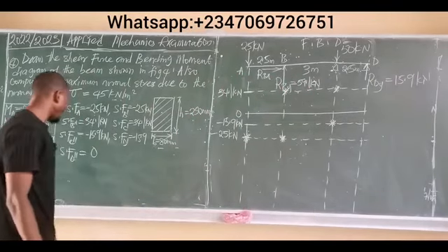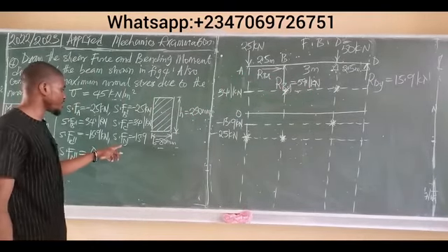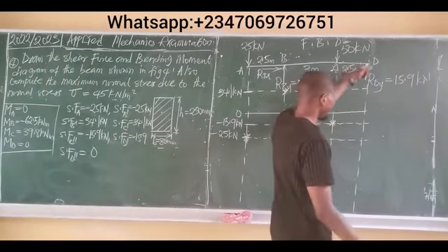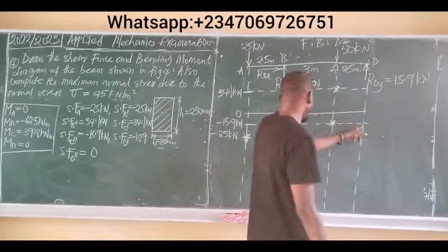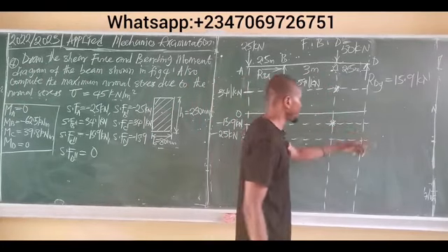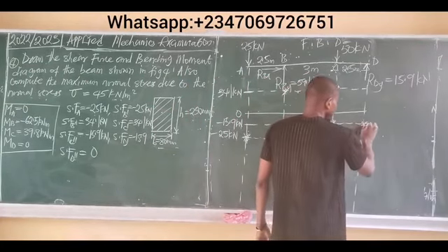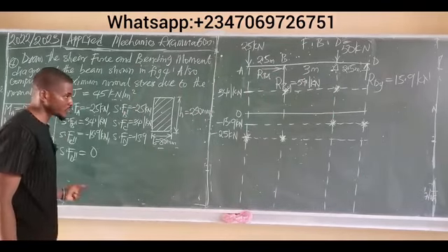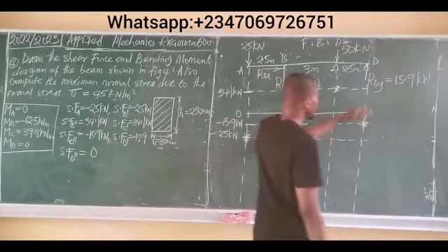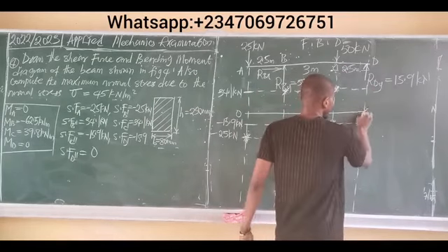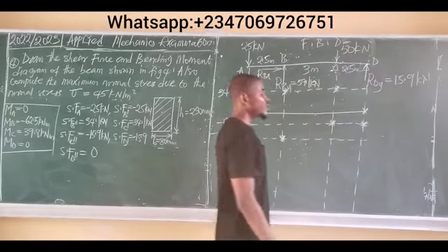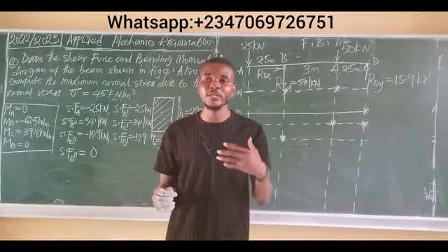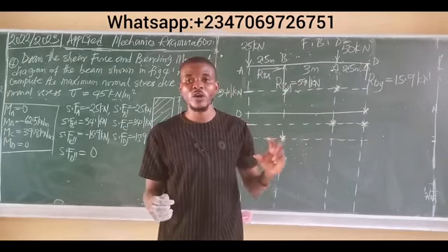Shear force at D prime, which means initially at point D, still remains minus 15.9 kilonewtons. This is line D. This is minus 15.9 kilonewtons. So this is where they meet. You simply asterisk. And finally, shear force at D double prime gave us 0. So this is line D. This is the 0 mark. You simply asterisk.